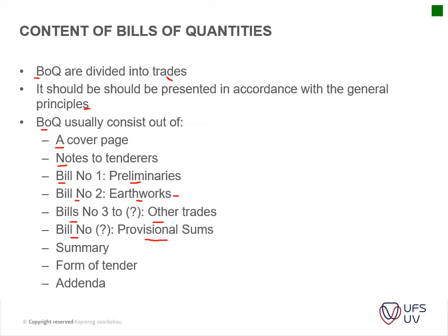So for instance, you would allow 100,000 for your air conditioning, and then the contractor should get 3 quotes, and those 3 quotes are evaluated, and the best contractor appointed according to those quotes, and it should be within the budget allowed. If it's over the budget, then usually a variation order is signed.